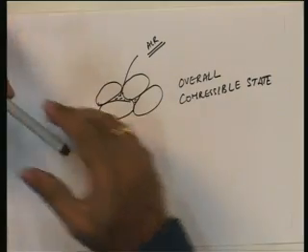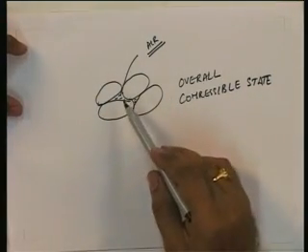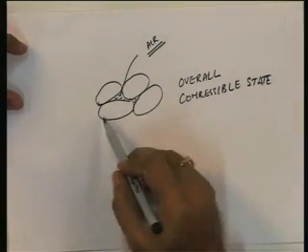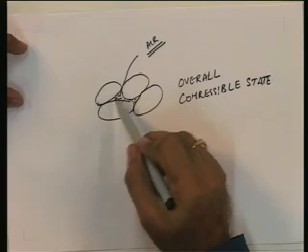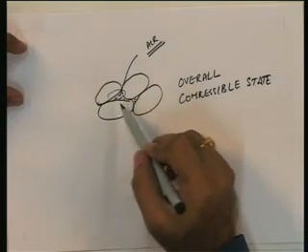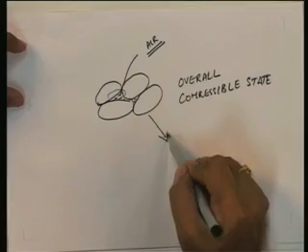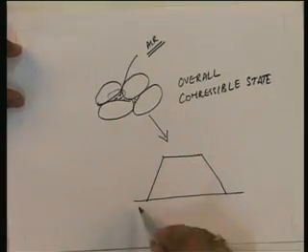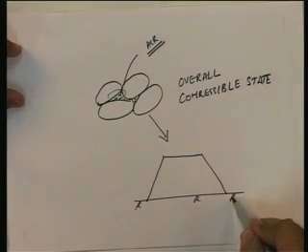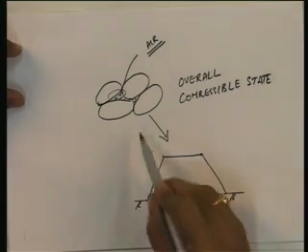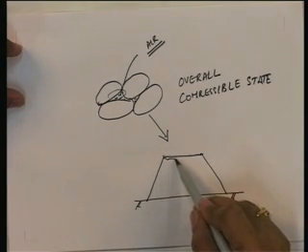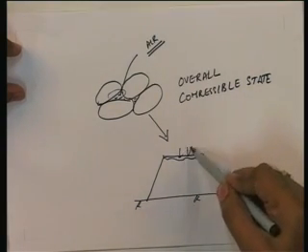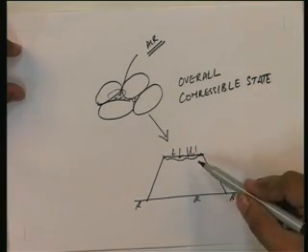When it is subjected to stresses from further layers of fill or a structure, the soil is actually in a potentially collapsible state, because with the stresses these particles will try to come closer. In the process, for example, if this is an embankment of certain height, the embankment can be subjected to some settlements. So, it may lose its serviceability.